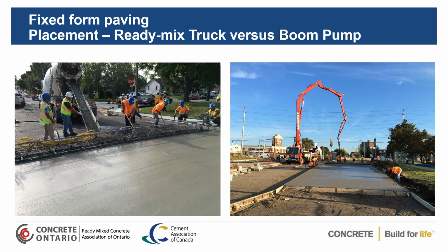So when we're looking at ready-mix truck delivery versus a boom truck, if you have no impedance to delivering the material, a ready-mix truck is fine to deliver your material. See here we have a vibrating screed that's being used to consolidate the concrete. Then you have the ready-mix truck providing that material. Another way to do it, here they've got quite a width that they're dealing with, so they can do a side load via boom truck, so that they're providing the concrete that way. Either one works.